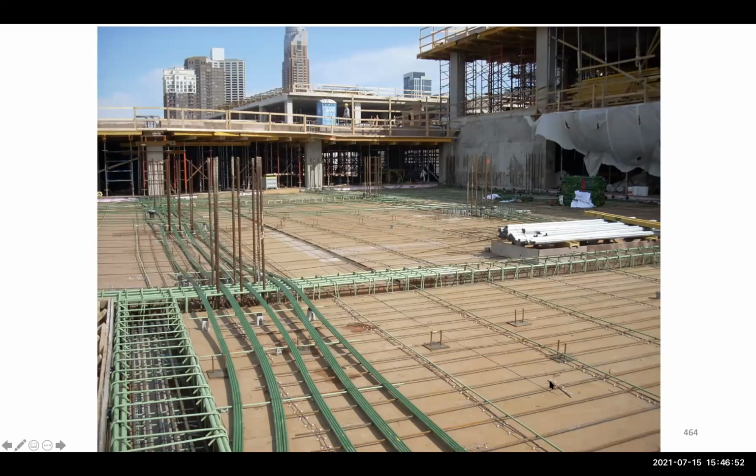So here you can see some of the inserts. You have a couple of studs in the plate, so you can see where they are put, right? When they cast the floor, you should be able to see these from the bottom of the floor, and then you can use it for whatever application, like hanging equipment from the slab, so it can be welded or connected to these plates.